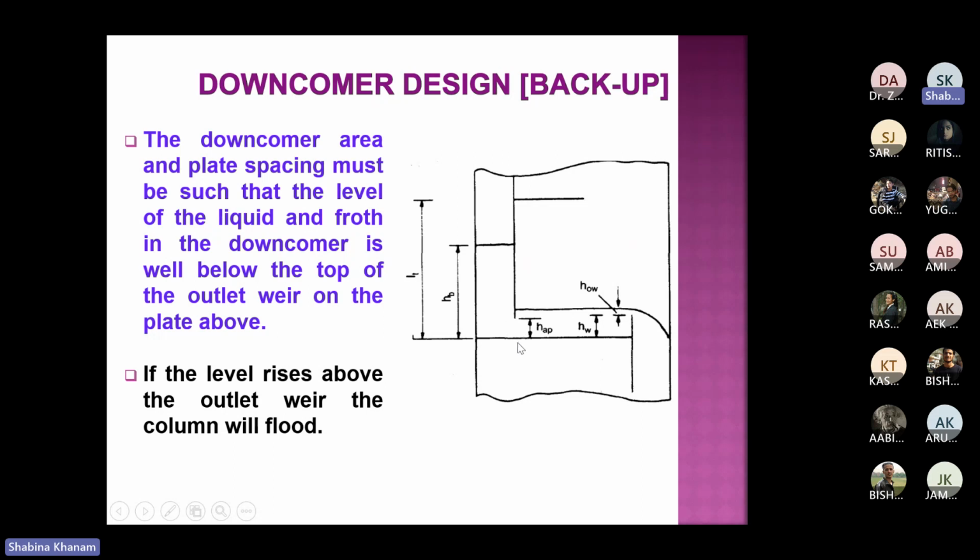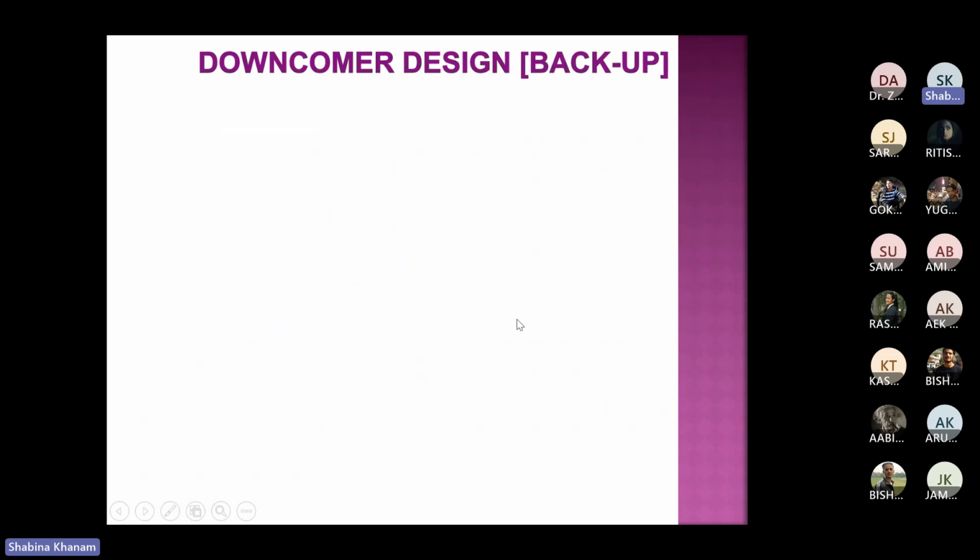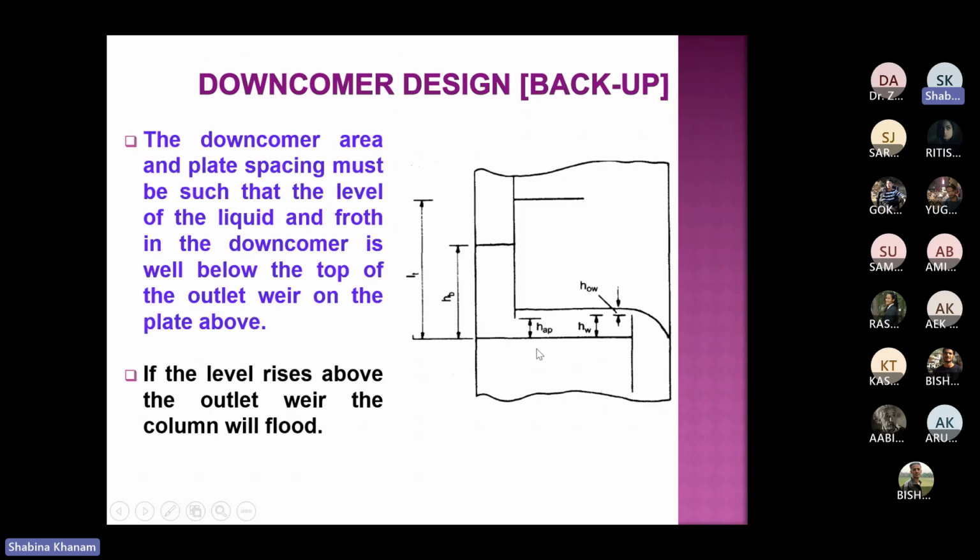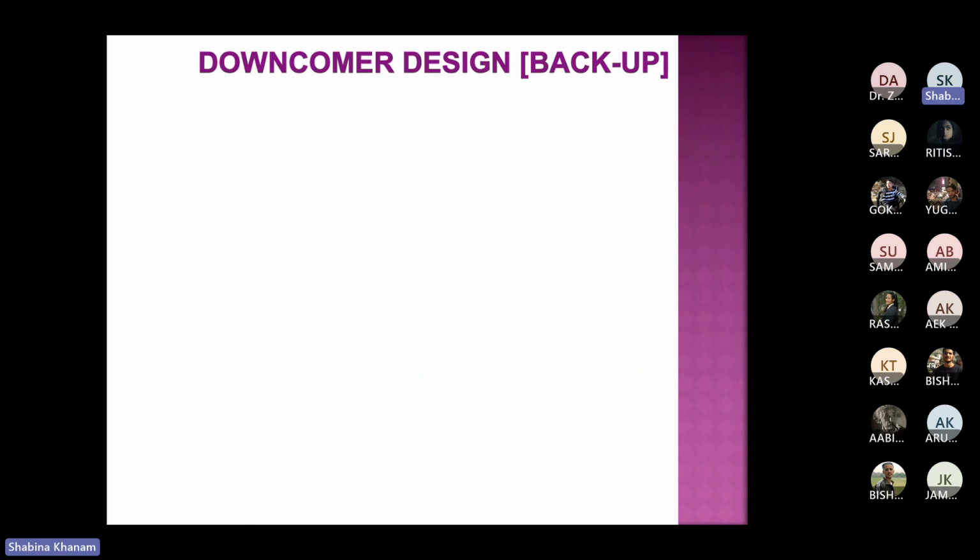If you would like to calculate, you need to consider the weir length. Sorry, what I'm saying is that the weir length should be the cut part of this plate, and that LW we have already seen in the last class how to find.